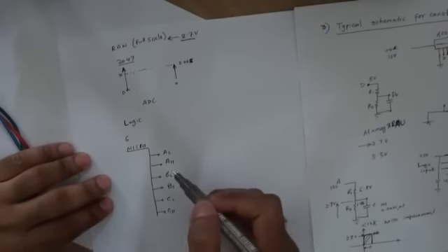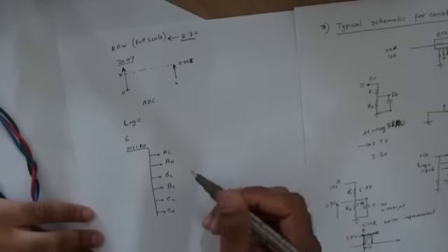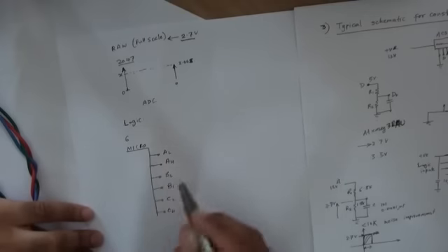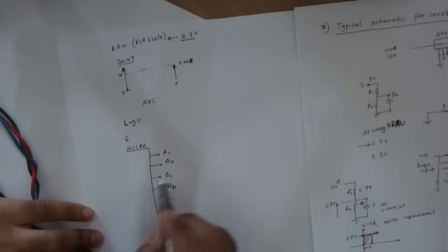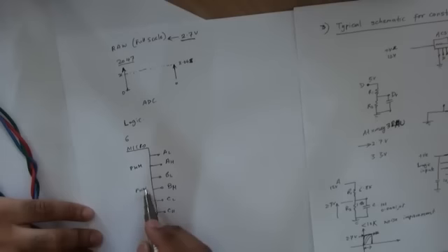To drive a BLDC motor in sensorless mode, you have to make sure you drive the high sides with PWM. So this is the high side. You have to make sure that you have PWM on the high sides only, and only high sides.